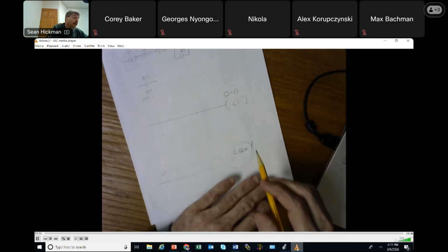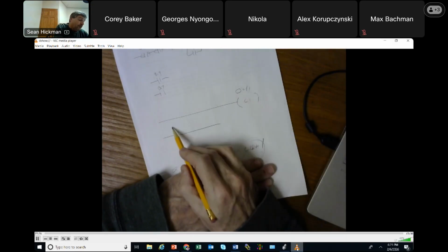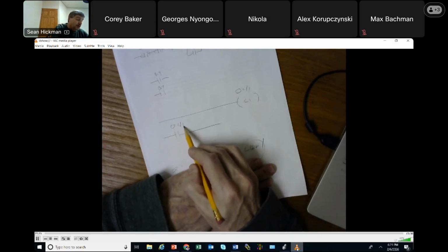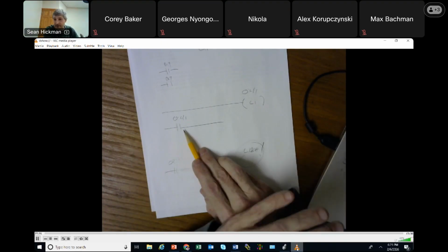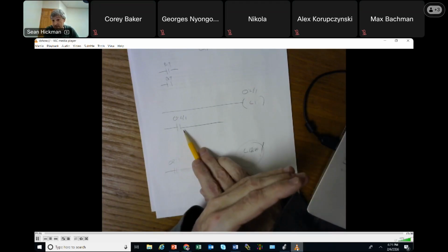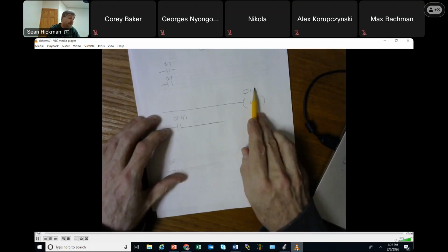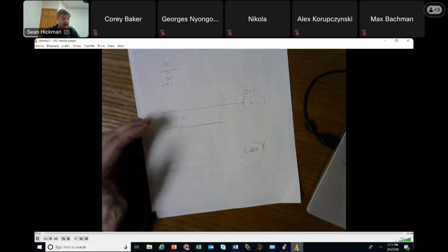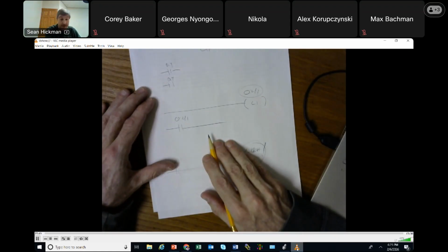Okay. So here, if I did this and then I use output 2/1 as a contact in there, it's getting to be fuzzier if it's going to get written at the same time, because this is going to be on the IO scan. All the ladder logic's going to be on the ladder scan.